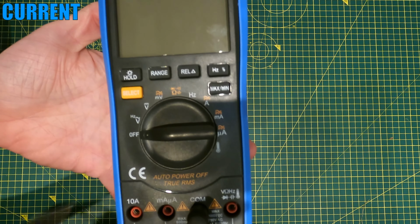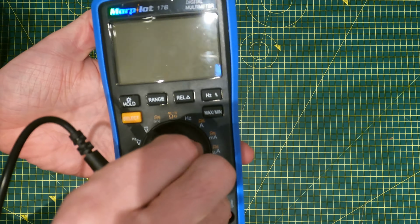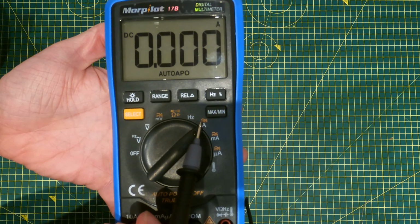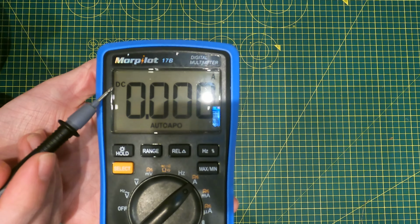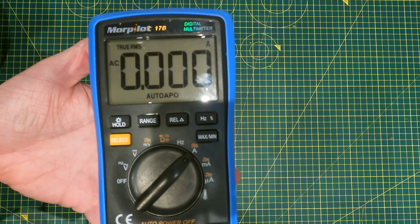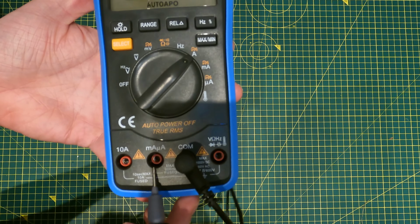And finally we've got current, which is indicated by the A ampere symbol. So what we do is we get our selector dial, twist it over to the A. You've got two symbols, you've got the AC waveform and you've got the direct current underneath. And it will show you just there, DC at the moment. If you press the select button, that'll change it to AC, so you can use it for whatever application you wish. At the bottom you've got two terminals.